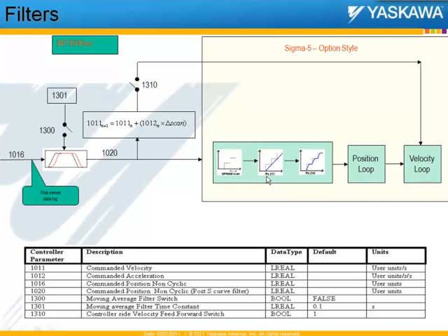Instead of parameter 812 in the servo pack, we use parameter 217 for moving average or linear sub-interpolation, and parameter 216 for exponential sub-interpolation. You need to use only one of these two. You don't have to use both. By default, these are set to 0.